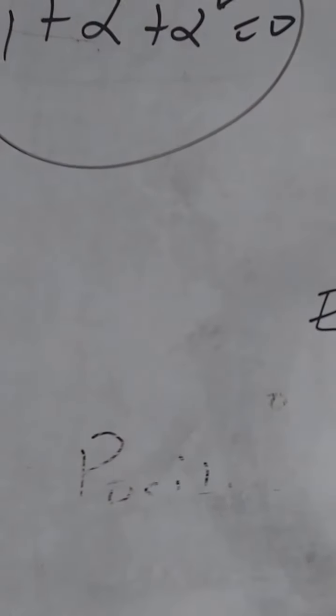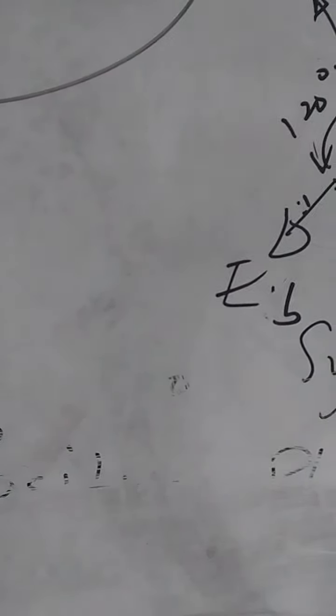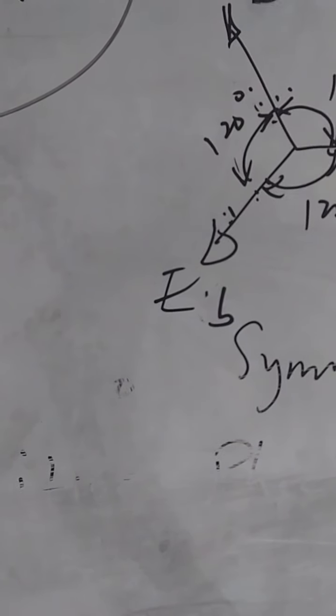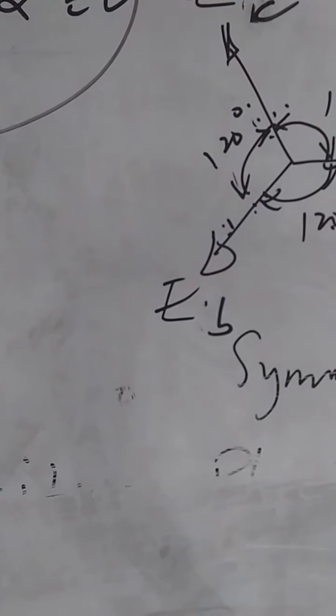Now, let's move to the resolution. If we want to resolve an unbalanced three-phase system of phasors into its symmetrical components, let's take this one as the phasor diagram of the original system with a positive phase sequence. Now, the original system will be resolved into three symmetrical components.